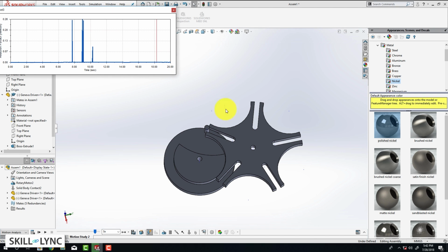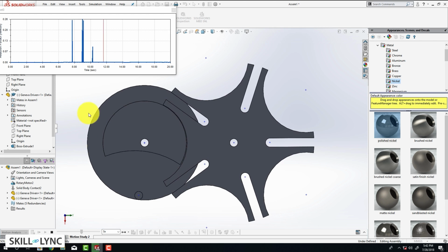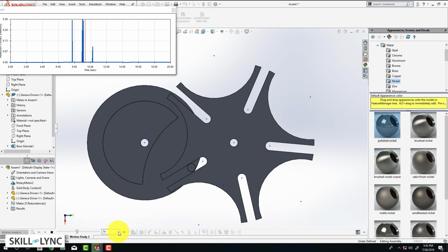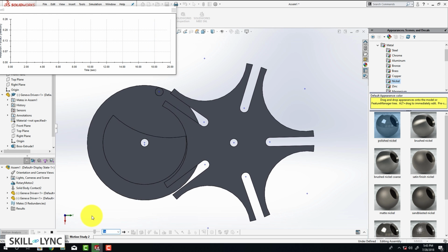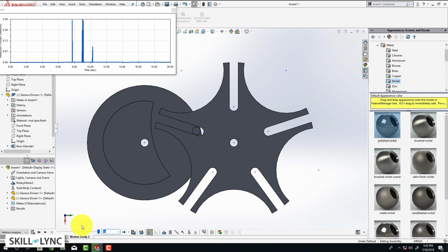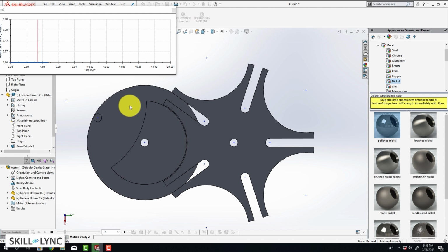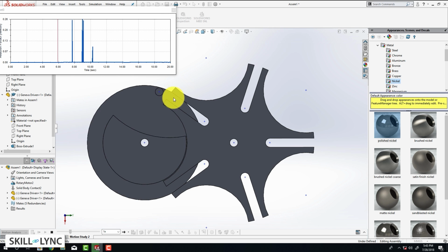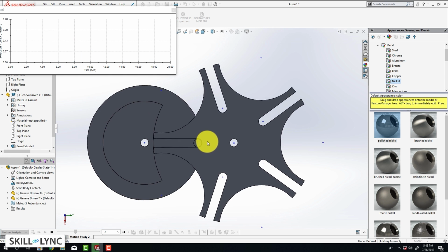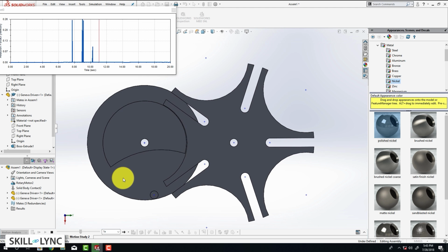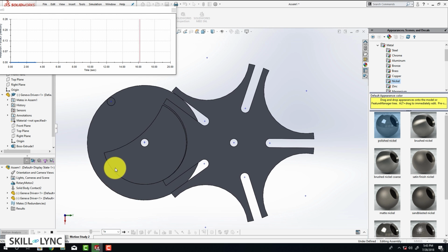Now you can move the graph to one corner and hit the play button. The advantage is that you can see at which part of the motion the contact forces are exhibited. This helps us fine tune the component motion, and maybe even reduce the speed of the animation so that you can exactly understand the dynamics of the problem. Subsequently, you can take these force values and run a structural analysis calculation with it, but that is not something we would be focusing on.